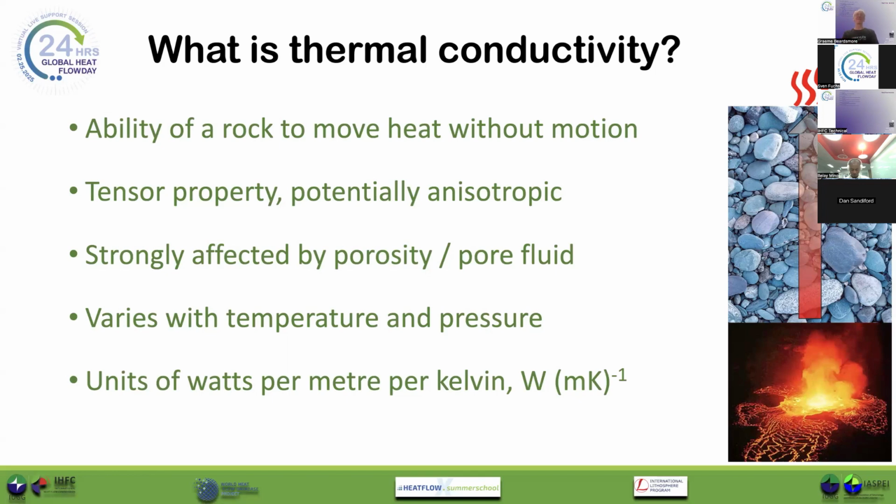Another characteristic of thermal conductivity is that it is strongly affected by porosity and the type of fluid that is in the pores of the rock. Rock minerals tend to be more conductive than water. So the more water you have in the rock, it generally reduces the bulk thermal conductivity of the rock.